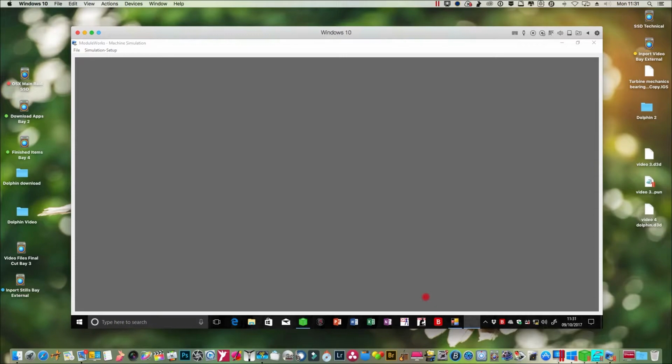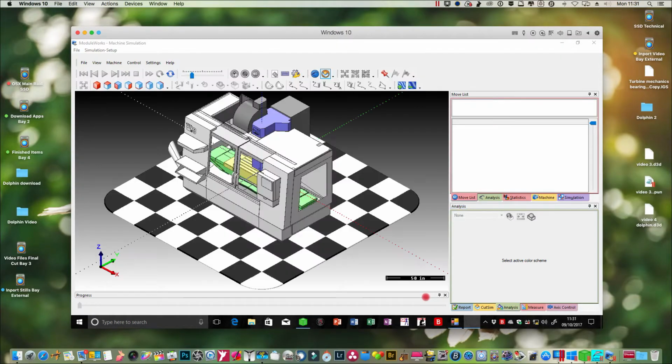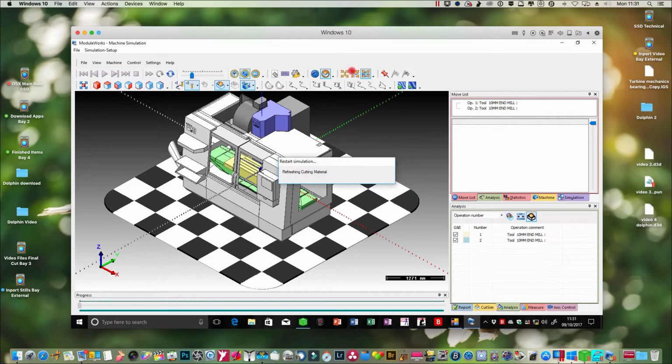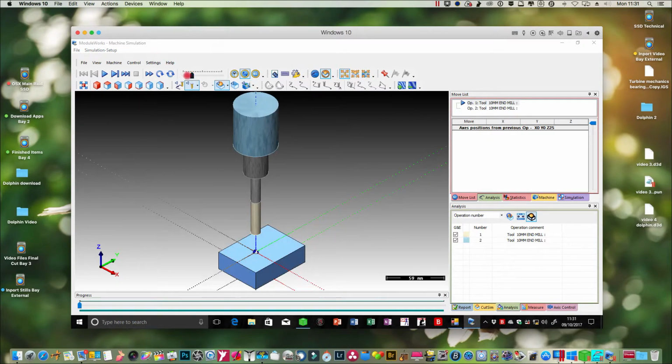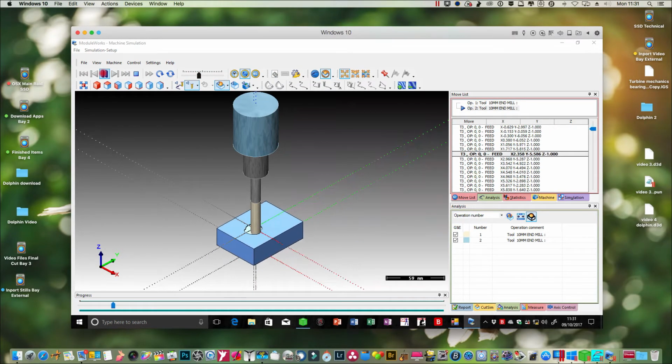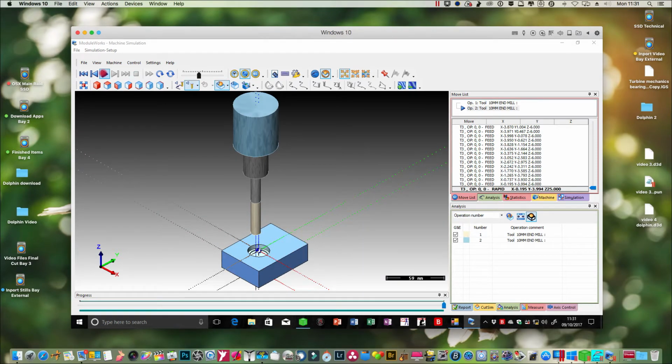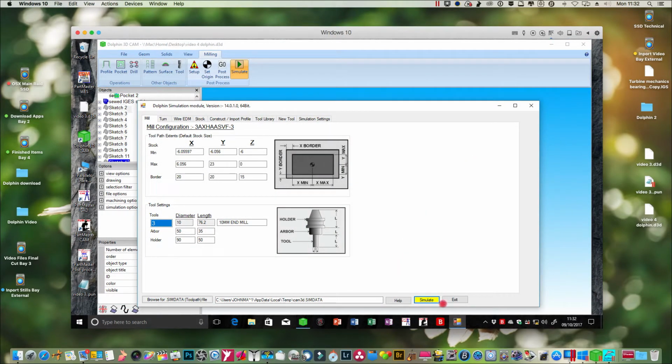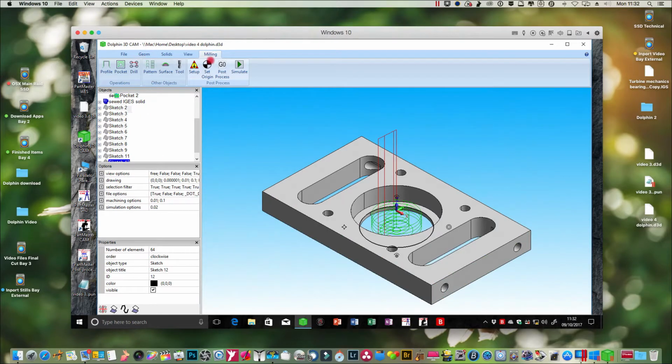Simulate. So like that. To speed, so we're saving a bit of time. It's going to do a step down 6 times, and it's coming up 25mm, which is a clearance for your clamps or whatever, which happens to be 25mm for a tool change for B. So we come out of that and get 6. We now post-process.